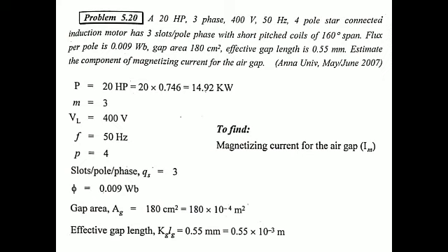It is nothing but a star connection. So you have to concentrate on voltage. The current should be the same here. Then the next one, slots per pole is 3, which is nothing but the Q value. Then with the slot pitch, a coil span of 160 degrees. This is all the data needed to find the alpha value. So we will deal with this in the proceeding.